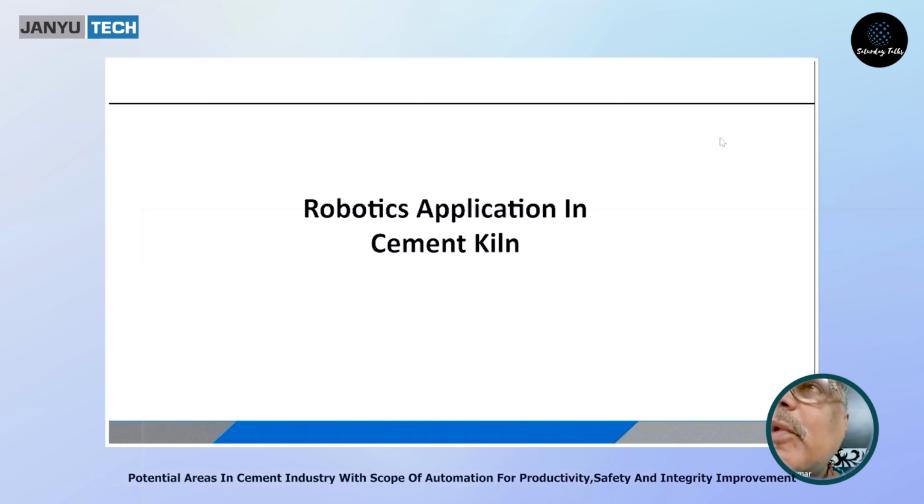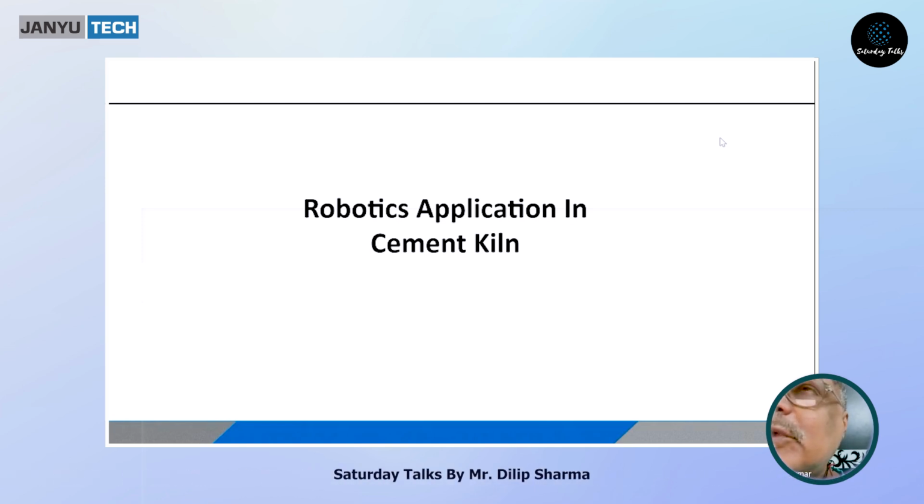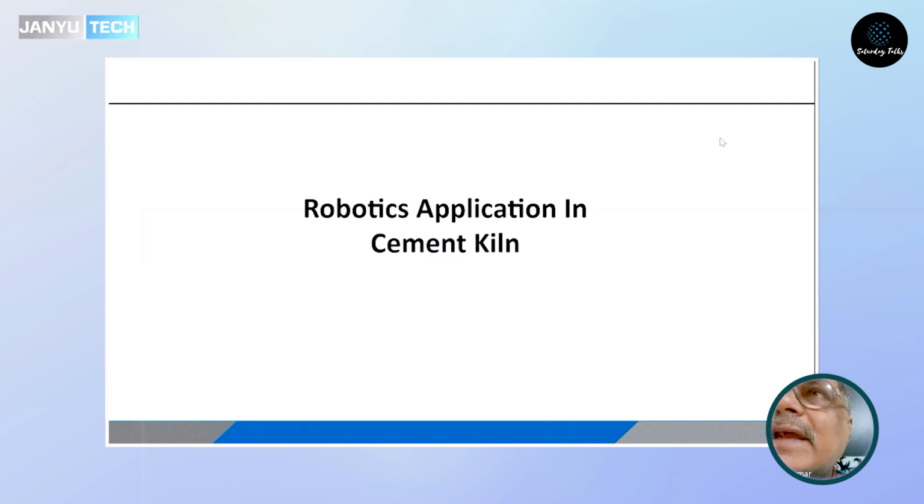In cement silos, the major problem is, during monsoon and even otherwise, the cement, especially slag cement, which is manufactured by using almost 70% slag, which comes from steel industry, that contains almost about 12 to 14% moisture.